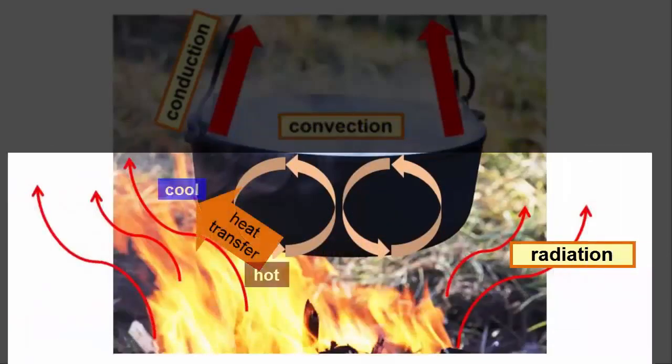During radiation heat transfer, electromagnetic waves are released from a hot source and spread outwards through space in all directions. When those waves collide with other objects, they excite the molecules in those objects and raise their temperature. Heat is radiated from all objects with a temperature, that is, from all objects whose molecules have any internal kinetic energy at all. Thermal radiation is generated when heat from the movement of charged particles within the atoms is converted to electromagnetic radiation. This image shows, and we know from personal experience, the radiative heat that's transferred from a hot fire to the objects around it.